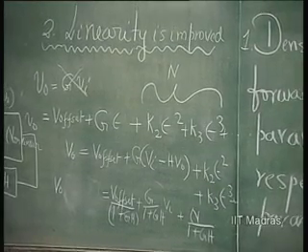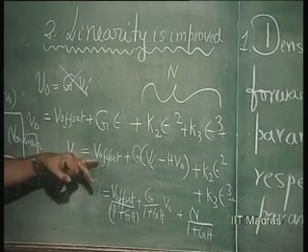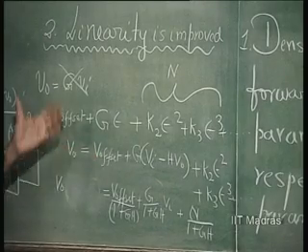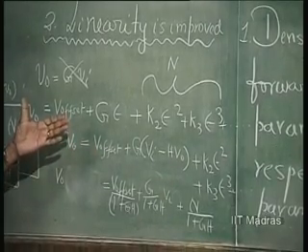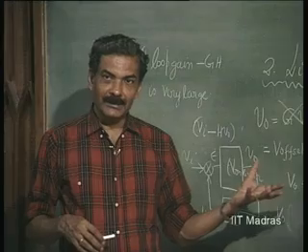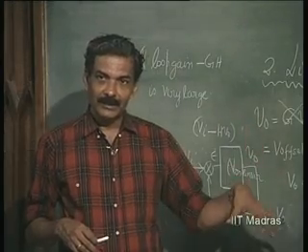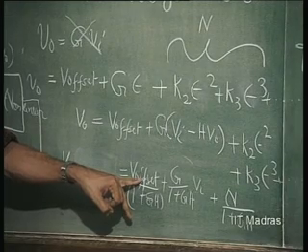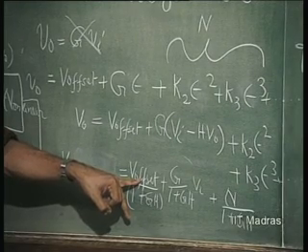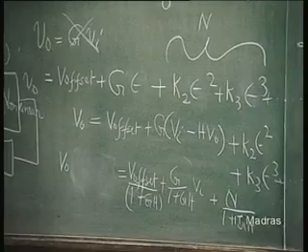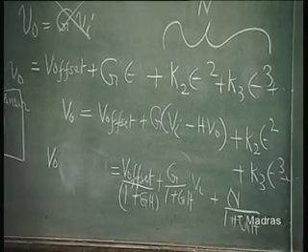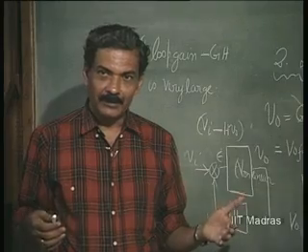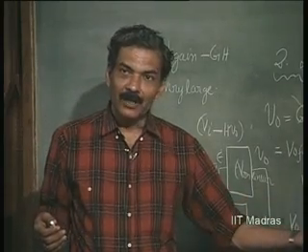So, that means anything that we add externally now, all these things apart from the signal will get reduced. Even the noise generated is going to get reduced. Offset can be also treated similar to noise that is internally created, right. So, because this offset may be temperature dependent and it might be varying with respect to time in an arbitrary manner, it is equal to certain amount of noise.